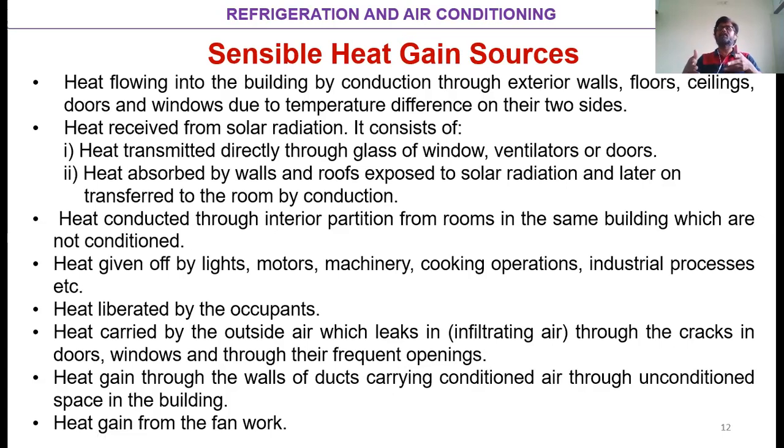Heat will be conducted, rather. Heat transfer will take place by conduction through the finite thickness of the wall, floor, ceiling, doors, and windows. Because all these components will be made up of a material having a lower thermal conductivity. Even though they are poor thermal conductors, still some amount of heat would be dissipated from the surrounding into the space that is to be conditioned. Isn't it? So it will be essentially transferred by conduction due to the temperature gradient delta T across the wall. So, direct heat addition.